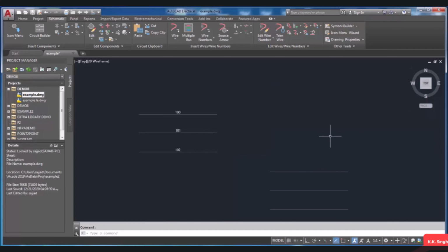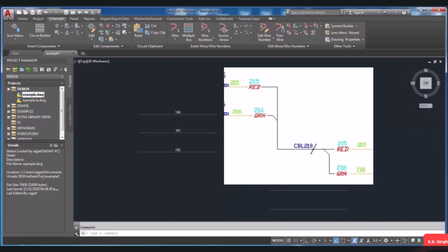As you see, with the help of AutoCAD Electrical in such instances, the fan-in source and fan-out destination can be used. As you can see, the wires come together and form a cable, and at the end of the cable you can see similar wires that come out from the cable, and in the middle of this sketch is the cable. So it is obvious that fan-in makes it possible to convert multiple wires into a single line.